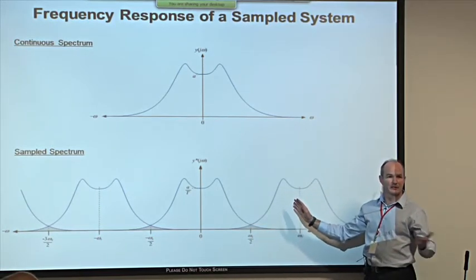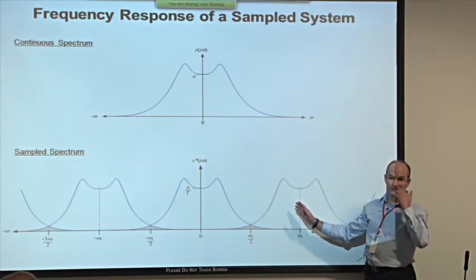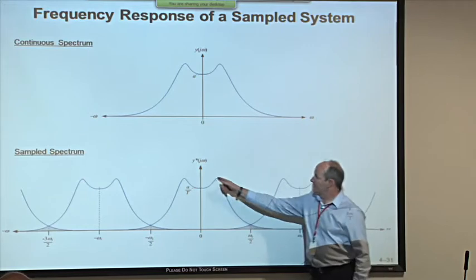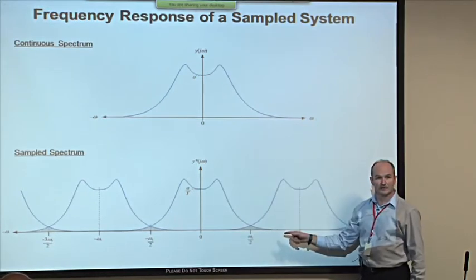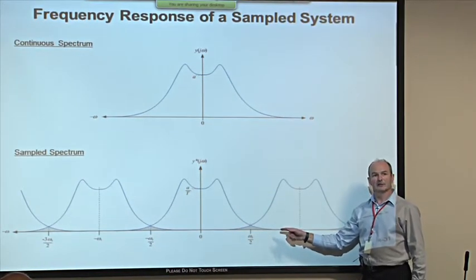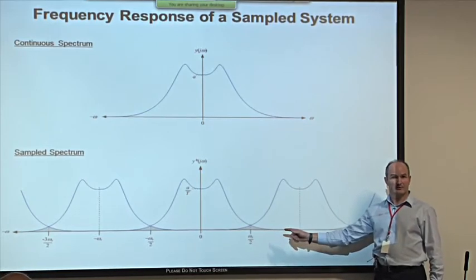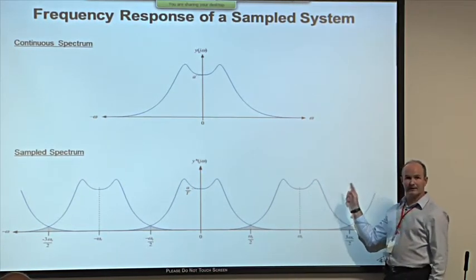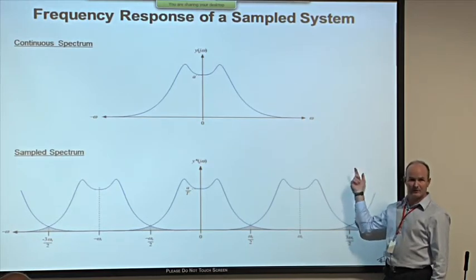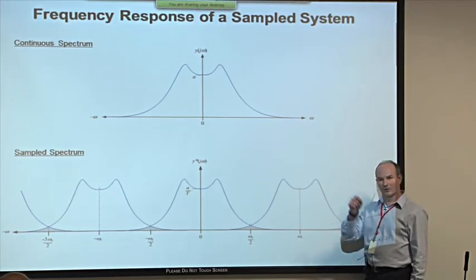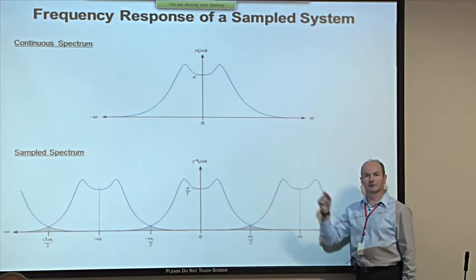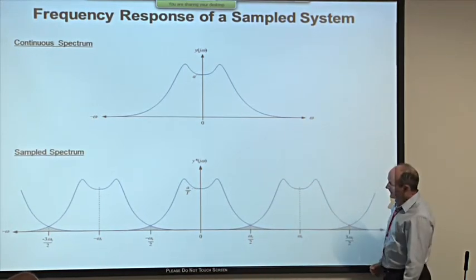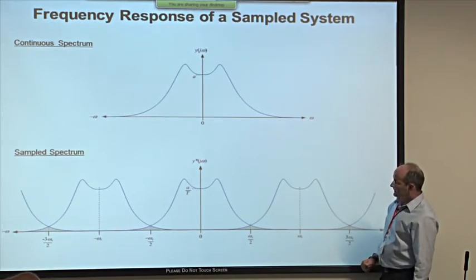In terms of the sine wave example that I showed you a couple of slides ago, we had a sample frequency of 40 hertz, and yet 5 hertz and 35 hertz looked exactly the same. So can you see now the next sampled signal would have been 45 hertz, and then 75 hertz, you were right, 85 hertz, 150, 125, and so on. Those are all frequencies that would have given you exactly the same set of data points because of aliasing.